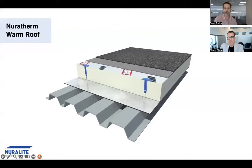But that metal tray, coming back to the focus of this webinar, thinking about how we can design and build roofs that are more cost conscious, that's by far the most cost-effective substrate to use. And the other benefit, obviously, with the warm roof, you're putting the insulation outside of the roof structure, which is where it should be, really. You're eliminating the risk of interstitial condensation. And you've also got a really good uniform layer of insulation there.